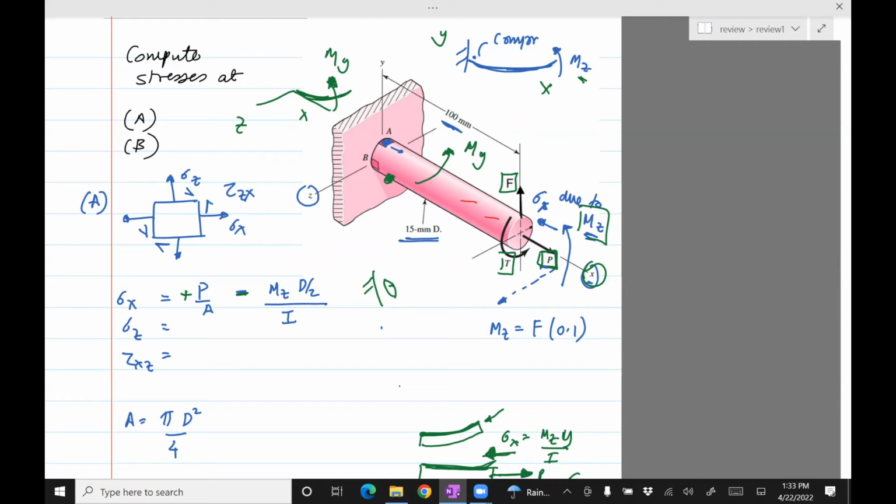So how do we know how it's bending, and how do we decide where the compression and where the tension is? You just look at the side which is convex, or concave, which is confusing. Think of this as a U, a half U or a cut U. Whichever side is the inner side of the U is compression, the other side is tension. So the way it goes is, first I figure out the direction of Mz, then I bend the beam in the direction of Mz.